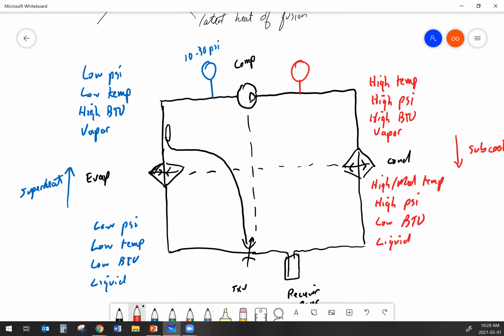It can vary easily anywhere between about 150 and 350 PSI. If your air conditioning system is operating and it's really cool outside, you might even see lower numbers than 150. If it's really hot outside, maybe it'd get higher than 350 depending on how well everything else is working.